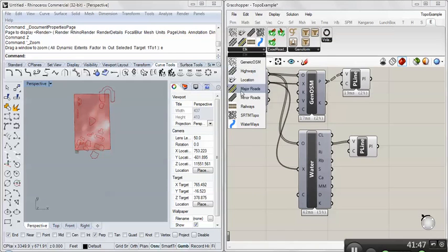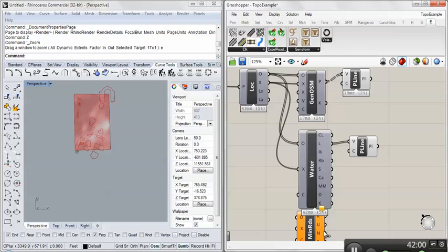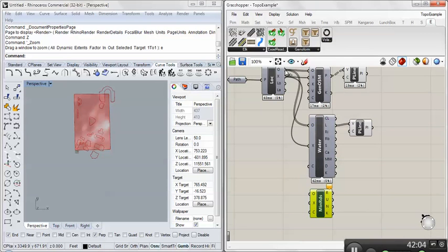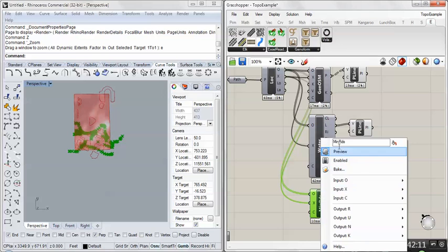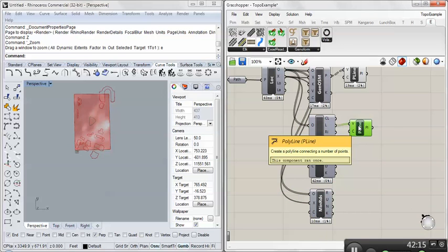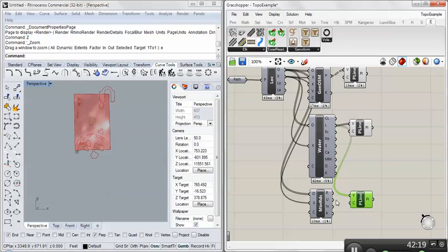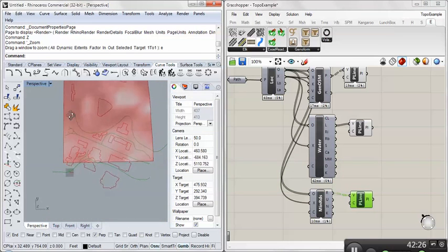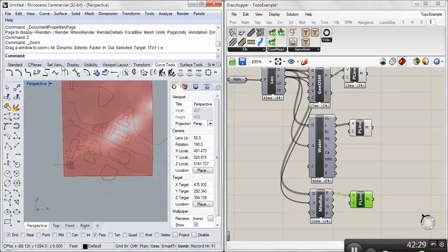The last one you can grab is roads, major roads. They both work the same. Highways, all three of them. In this case, I already checked. It doesn't consider there being any major roads on campus. Everything's minor road, so you don't have to grab the other one. It's empty. Then same thing, grab the O, grab the X, hide that, and copy, paste. Okay, so there's the road it grabbed. We're just off of whatever that road is, so it didn't capture it in our set. But we have Jayhawk Boulevard, all of these ones down underneath.